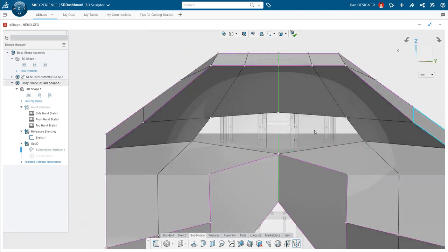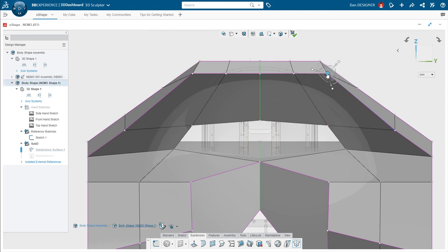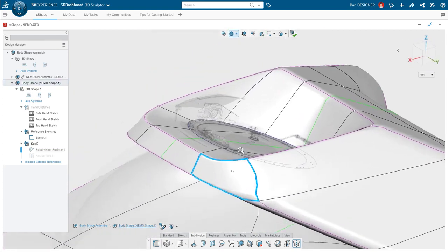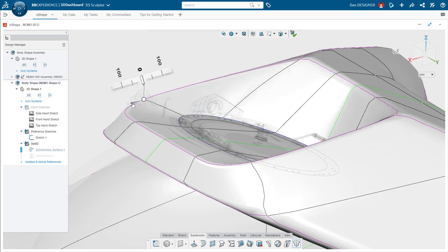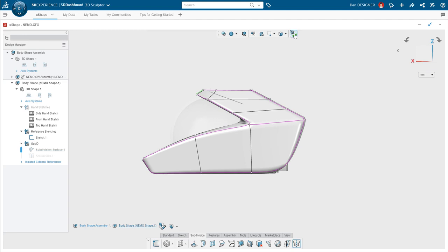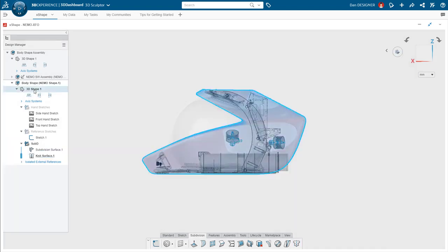To leave the coincident faces undisturbed, Dan can once again reposition the robot accordingly. Dragging the webbing of the robot will ensure his translations maintain the coplanar alignment of the faces. After a few more adjustments to the hood, Dan is ready to tackle the pathways on the side of the design for the thrusters. He'll prepare a set for each one, not just for organization, but also to sever their dependency on the order they exist within the design tree.